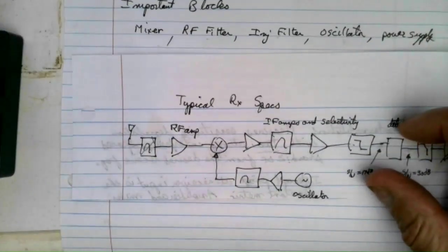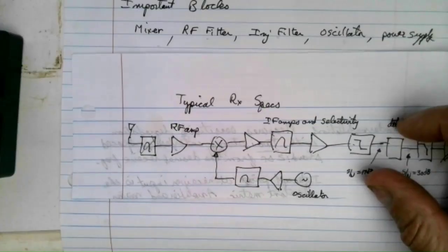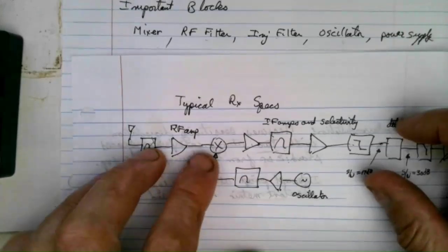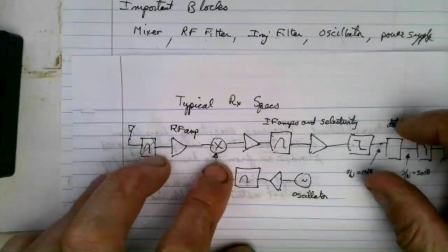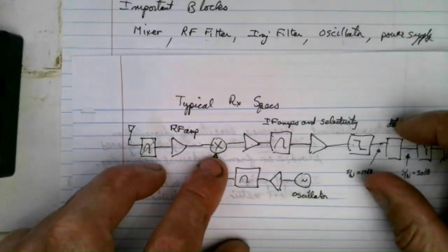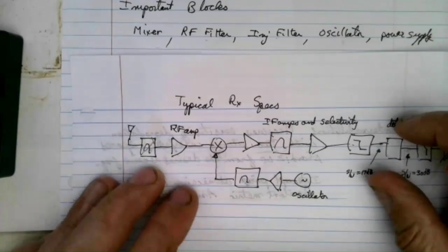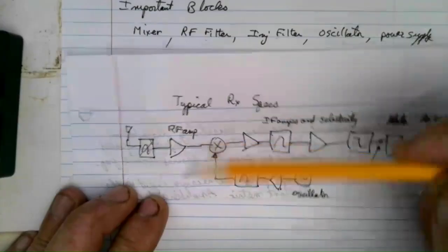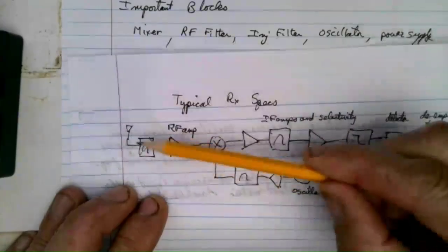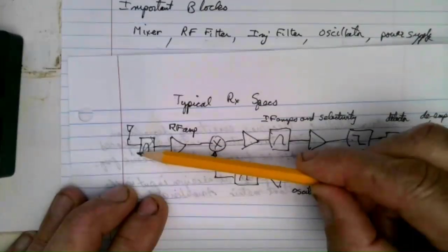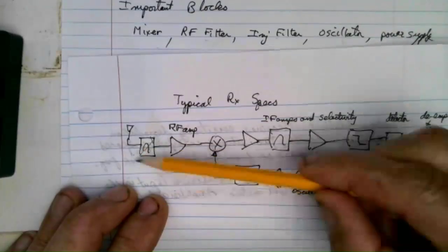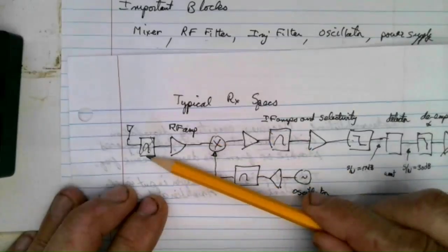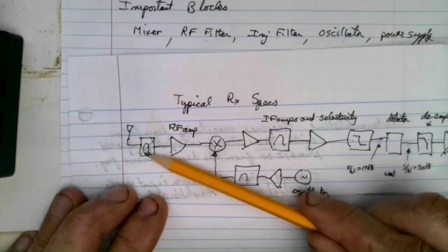Now, the last thing I want to mention is just the design. All right, so naturally, given the design, you choose the best components that you can get. But if you're really bad about choosing design, like they were when they designed the broadcast FM band, you set yourself up for failure. And here's an example of how you set yourself up for failure. You design yourself a 20 megahertz band here, the broadcast FM band from 88 to 108 meg, with a 10.7 megahertz IF, so that the first mixer image is virtually in band.